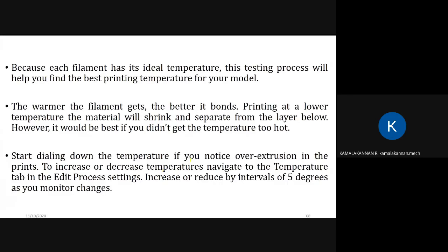Start dialing down the temperature if you notice over extrusion in the prints. Even after reducing the temperature, if you still feel the extrusion is too much, reduce by 5 degrees Celsius at a time, as you did for increasing.